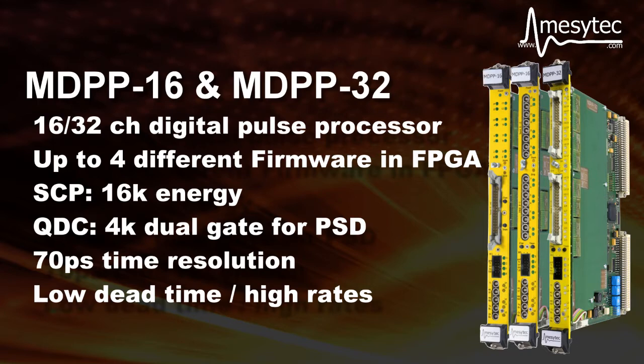Each firmware is emulating classic analog principles, thus no knowledge of digital signal processing is required. Up to 16K amplitude and 70 picosecond time resolution are achieved while having very low dead time, thus allowing for high data throughput rates. The QDC firmware with 2 integration gates allows pulse shape discrimination.